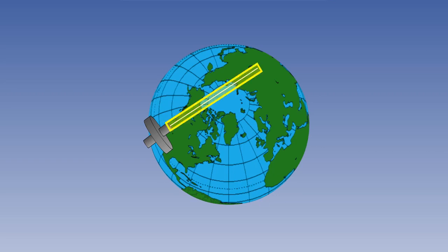This is the solid white line. The aircraft flies from Los Angeles to London. When the aircraft arrives in London, the gyro is still aligned with the same direction in space, the dotted white line. However, the actual direction of true north from London is the line connecting London to the North Pole.